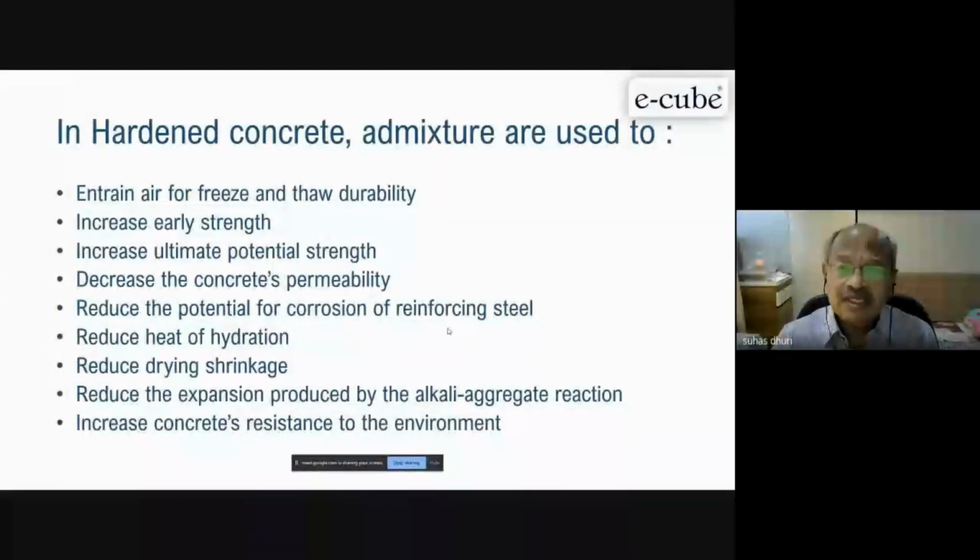Generally, civil engineers, in our experience, when you go to the site, anything goes wrong with the concrete. Suppose there is low strength, some strength issue, people go on adding the cement. So more cement is very bad for the concrete. More water is also bad for the concrete.